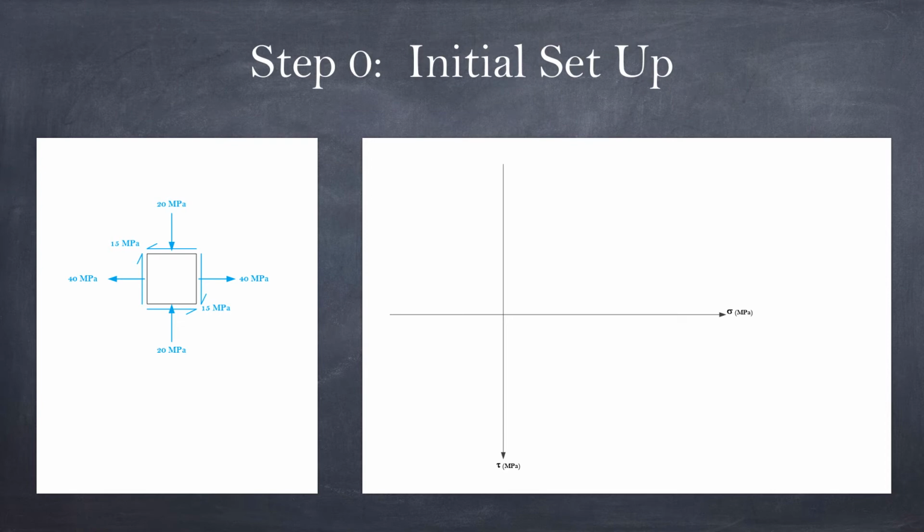The horizontal line is normal stress. Notice that I start to move away from axial and use normal, because it's no longer always axial, but just normal, which means 90 degrees to where we cut it, right? So basically, this will be normal stresses, and the right-hand side is positive. The left-hand side of the graph is negative.